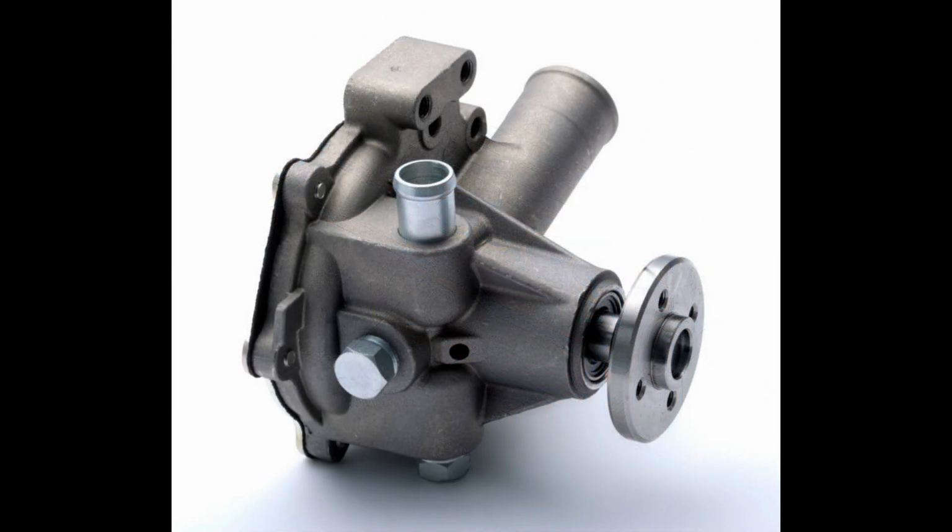But as the engine operates at higher RPM, the engine's temperature goes up, and so does the coolant's temperature. This coolant gets heated up to such a high temperature that it would create a high pressure situation in the radiator. If such high pressure keeps on increasing, it would burst the radiator pipes, which we don't want in any case. So to deal with this pressure, we have a pressure cap and a radiator overflow tank.